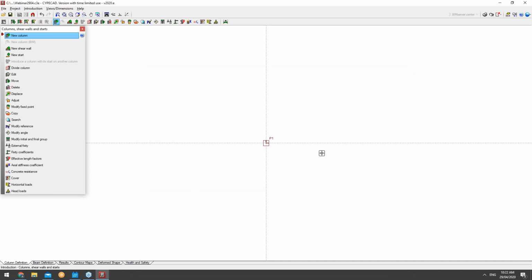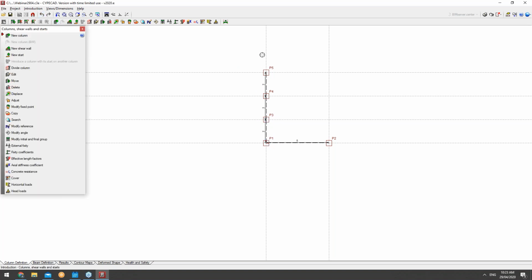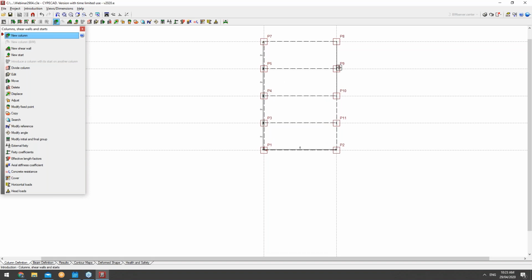So I'm going to create one in the middle. There's going to be one at 5 meters to the right, and at 2 meter intervals. Oh, the 2 meter intervals northways. Oh, I think I didn't do that. Here, come on. Perfect. And now I can, of course, just connect the opposite columns as well. Perfect.